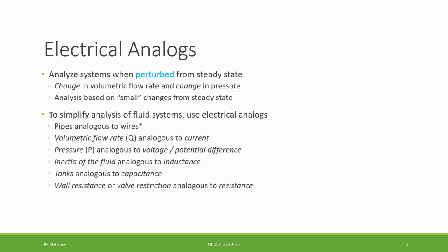We're going to have pressure or head pressure, and that will be analogous to the voltage or the potential difference. Again, in the electrical systems, voltage is in a way how hard the electrons are being pushed through our wires and through the elements. In fluid systems, that's actually going to be true. The pressure is how hard the fluid is being pushed through our different elements and through the pipes.